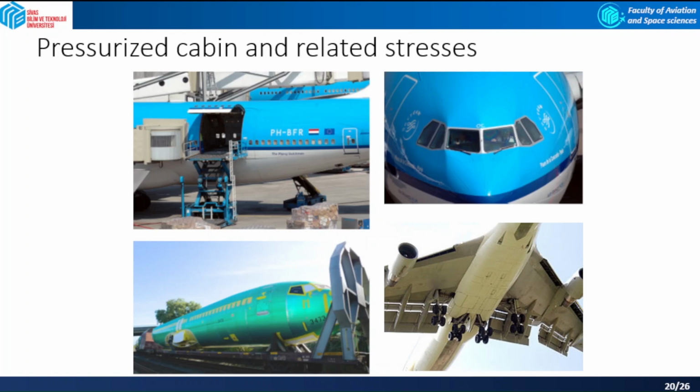Indeed, the calculations we've conducted so far have been based on the assumption of undisturbed cylindrical fuselages. However, in reality, aircraft fuselages feature numerous cutouts for windows, doors, hatches, and other components, and each cutout introduces a stress concentration, leading to higher local stresses in the vicinity of the openings.